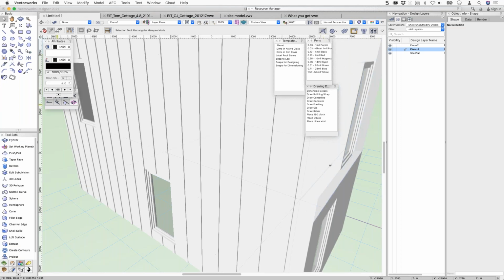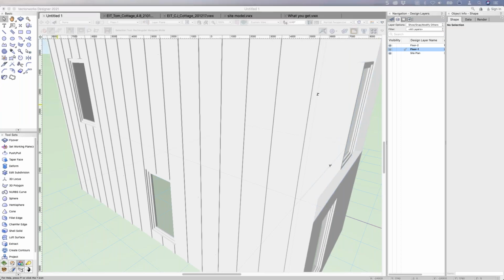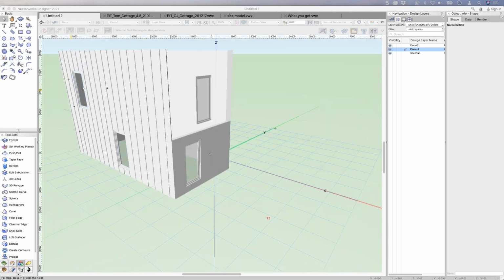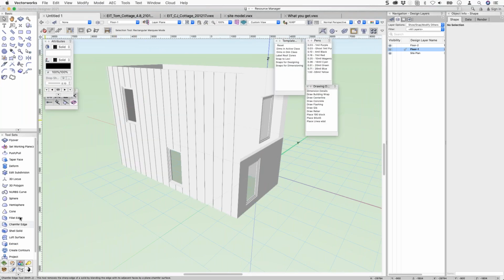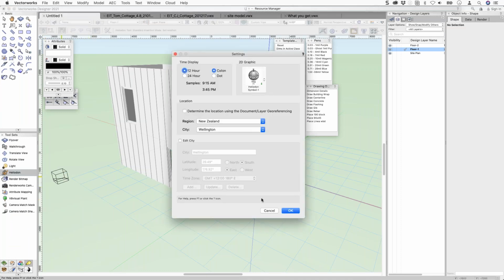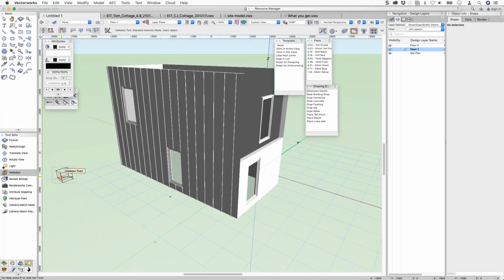And Andrew, there's another Andrew's got another question here, which is is there a way to get shadows to show on polygons in 3D views? I'm trying to think what you mean by get shadows to show on polygons. Are you using the polygon render? So we're using, and there's no sunlight in here, so I better put a sunlight in. I always use the heliodon to put in a sun. It's a really quick way to put in a sun.